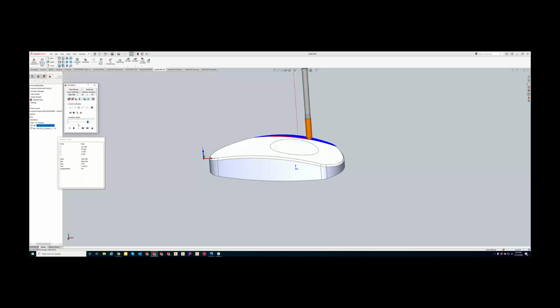So a little more work to get it to that point, but if time is a factor for you guys, then it'll definitely help out in speeding up this tool path across those large gaps. So right now we're at 1,000 millimeters, and we should start seeing this feed rate start bouncing up and down here.